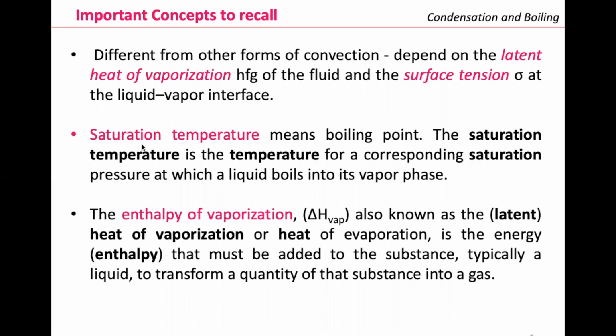Another important term to recall, saturation temperature means boiling point. The saturation temperature is the temperature for a corresponding saturation pressure at which a liquid boils into its vapor phase. Another important term to recall from thermo is the enthalpy of vaporization, or the delta H of vaporization. The enthalpy of vaporization is also known as the latent heat of vaporization or heat of evaporation, and is the energy, enthalpy, that must be added to the substance, typically a liquid, to transform a quantity of this substance into a gas.